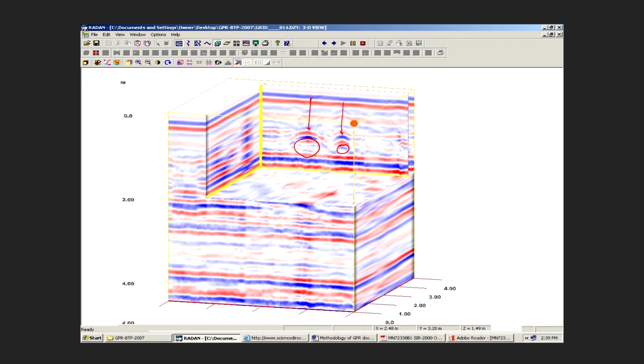So this is the advantage of GPR, and also I would say the advantage of taking the GPR survey in 3D. That helps you slice down at various locations in terms of depth, and then understand how the pipe runs, because you are having the data collected in the horizontal way also, and then you are having the vertical profile. So you can also trace out in which direction your utility or the pipe is aligned. That also you can do with this.